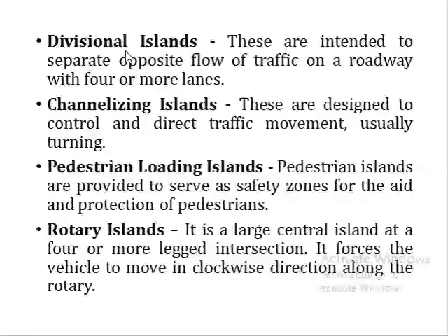Divisional islands are those islands which are used to separate the opposite flow of traffic on the roadway with 4 or more lanes. Whenever there are 4 lanes, 6 lane or 8 lane road, the opposite moving traffic is divided by a median or a divider, which are also known as divisional island.